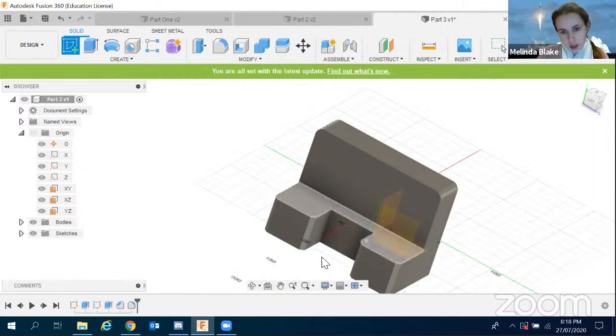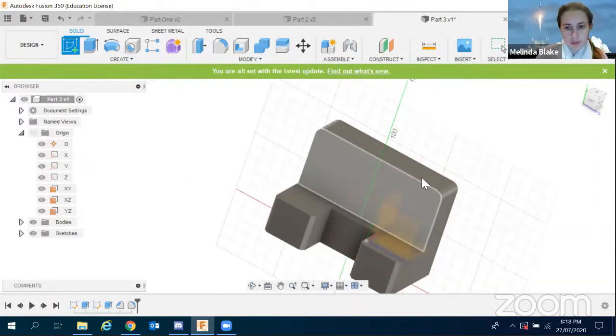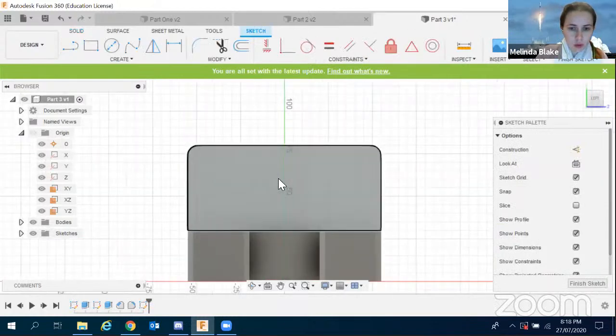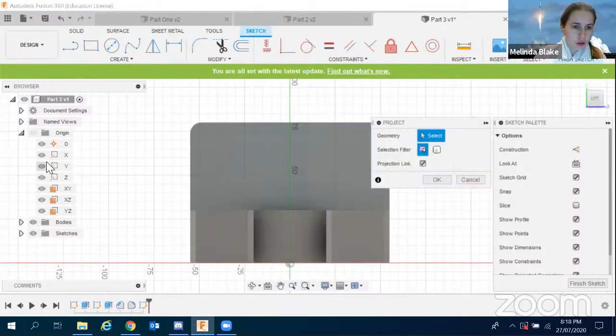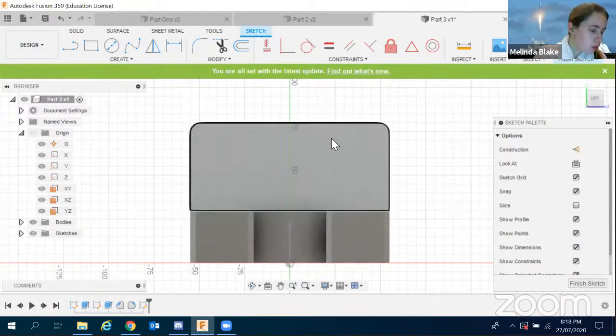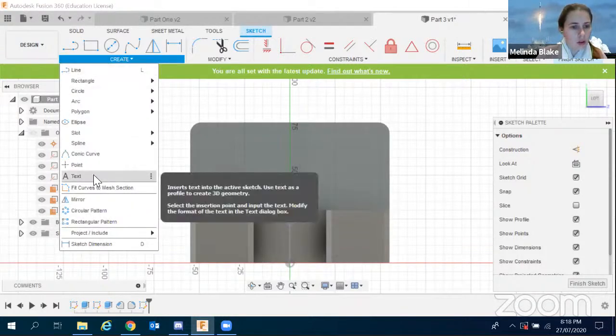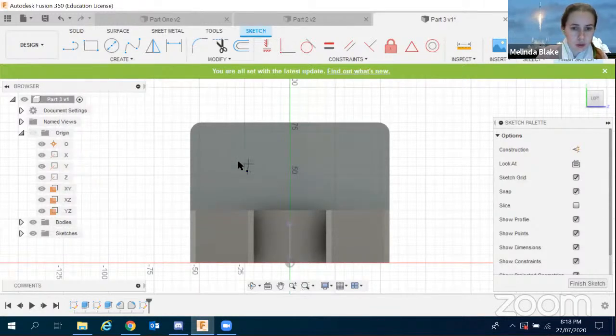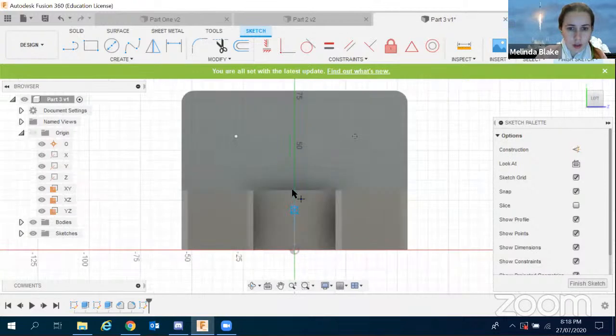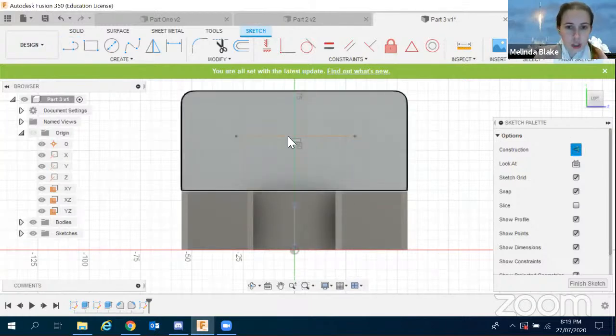I'm going to grab my create sketch, and I'll just place it on this surface here. Okay, might just start by projecting a vertical axis. That might be useful in the long run. Guess we'll find out. Okay, I'm just going to go in here, and I just want to mark the centers of the holes. So I'm just going to grab this point here. I'm going to plop 2 points down, just like that. Okay, now I know this thing is symmetrical, and I know that they're level with each other. So to make sure they're level with each other, I'm just going to run a construction line between them, like this. And just double check that that's marked as horizontal, and it is, so that's good.